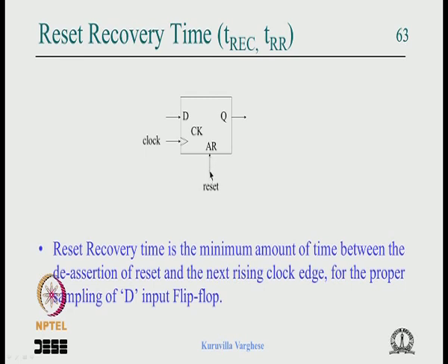So reset recovery is the time delay of that path where the reset is going and resetting the latch. Okay, if you analyze a detailed circuit you can find the reset recovery time in terms of the gates involved and so on. Okay, but I hope you get a picture of the situation. That's a problem, like you can assert at any time, with a delay it will be reset because it is going directly, it doesn't matter.